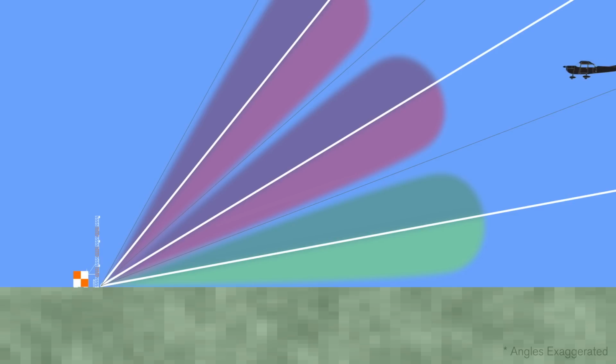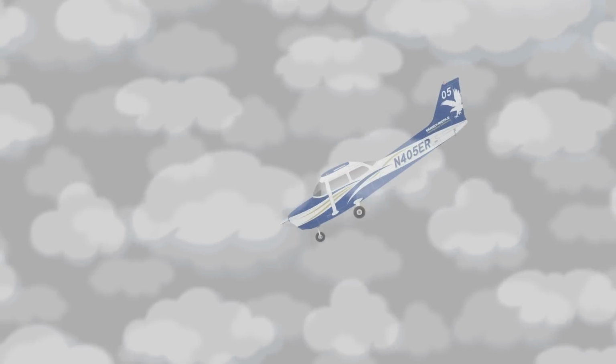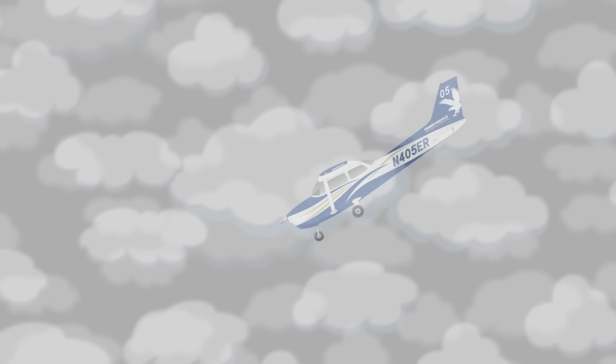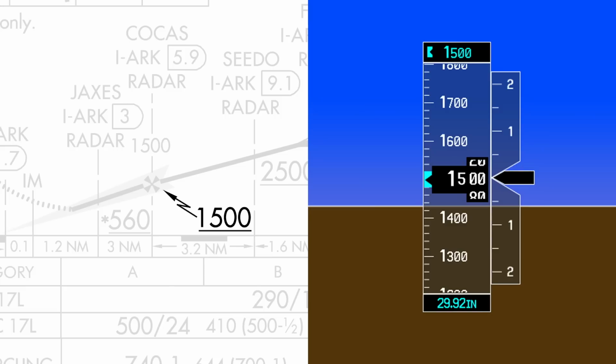Generally speaking, Glideslope intercepts beyond 10 nautical miles away may lead to you receiving a false Glideslope signal instead of the real one. Following a false Glideslope will result in an extremely high rate of descent needed to maintain it. Because of the potential of capturing a false glide slope, the correct procedure is always to capture the glide slope from below, and to verify the aircraft altitude matches the published glide slope intercept altitude on the approach chart.